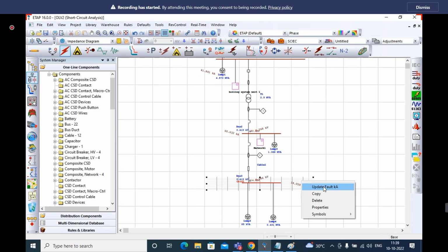While you are running the design, if you are going to do the earthing for single phase fault current, you can take it directly from that design. If you are going to do earthing for three-phase fault, you need to check the fault current from the design itself. You cannot feed it directly. From the user specified option only you can assign.